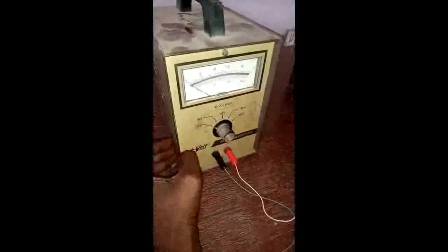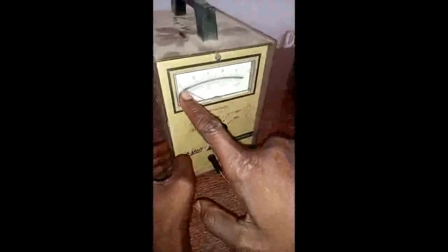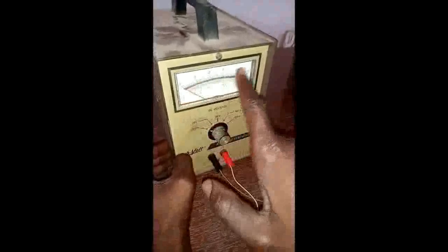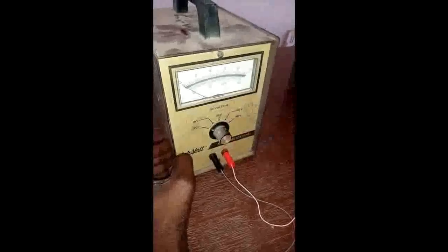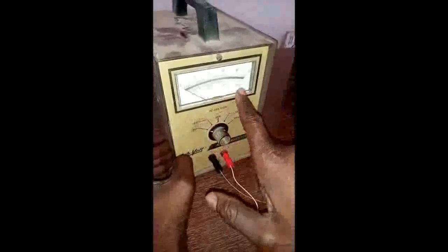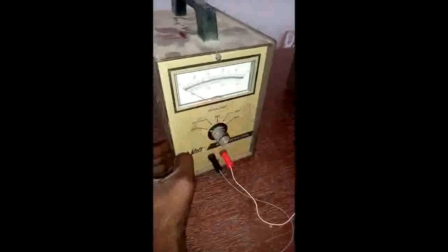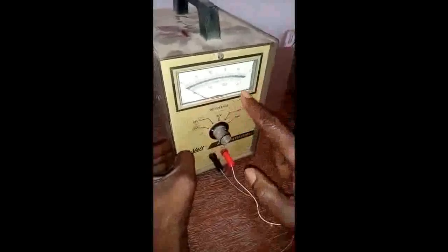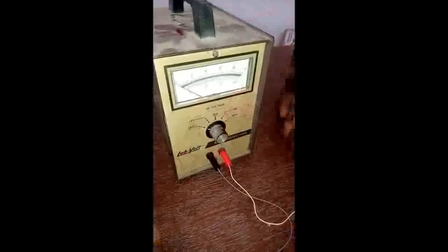So what must first come to your mind is that you look at it. Which one will be easier? Will it be easy to convert 0 to 10 to 3 volts or 0 to 30? Naturally, one will expect to use 0 to 30. So whatever you get there, when you use the lower range, lower scale, whatever reading you get, you just divide by 10. That one will convert it to 30. Because if you divide 30 by 10, what will it give you? Is it not 3 volts?